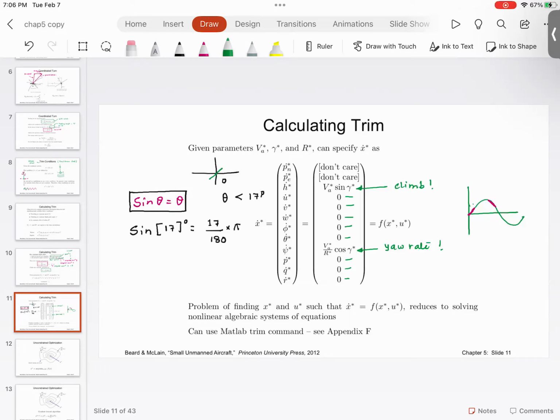He said that even if the system is nonlinear, if you are performing the linearization trimming at 1,000 times a second, in that teeny tiny time window, which they call a frame, the system behaves linearly. So even if you have a system which is nonlinear, you are looking at such a teeny tiny snapshot of the state trajectory that you can linearize it.